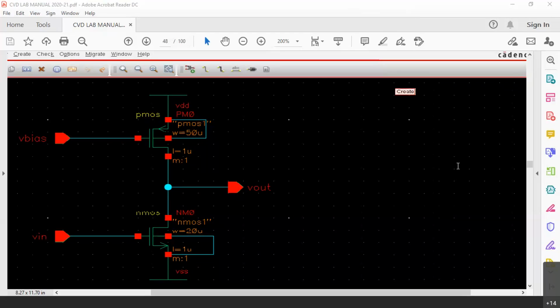So here, because we are connecting VDD at the top and we need the resistor at the top, we are replacing the resistor with the Pmos only, because Pmos passes good 1. If it is the other case, let us say the amplifying transistor is at the top and the resistor is supposed to be at the bottom, just like our emitter follower circuit, then we can use Nmos also there. That is the answer. It is not about mobility, it is not about large resistance. Okay.